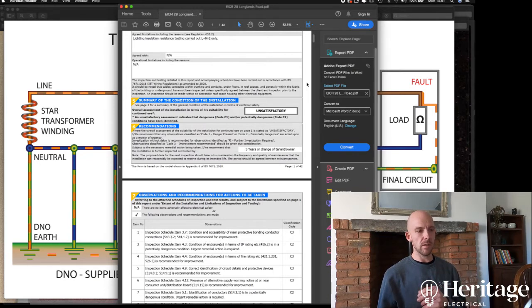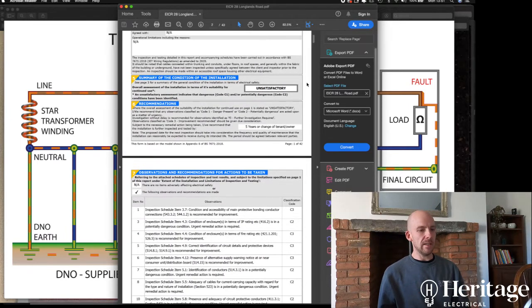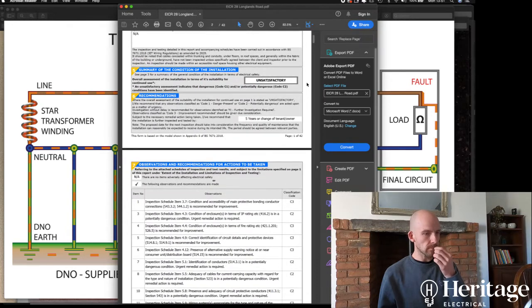So for some of the tests, specifically with lighting, rather than disconnecting all the downlights, removing all lamps, sometimes we will do it differently. We'll come on to this in a while, but insulation resistance is where we test the integrity of the insulation of the cable. When it comes to lighting circuits, there's a combined test that we do rather than tests between each individual conductor, but we'll talk about that a little bit later on.